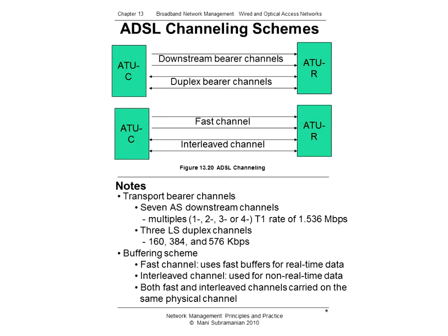The digital data that could tolerate delay use slow buffers that are interleaved between the fast signals. The digital data channel is known as interleaved channel, and a physical interface will carry both fast channel and interleaved channel, and it has to be addressed in the network management of interfaces.